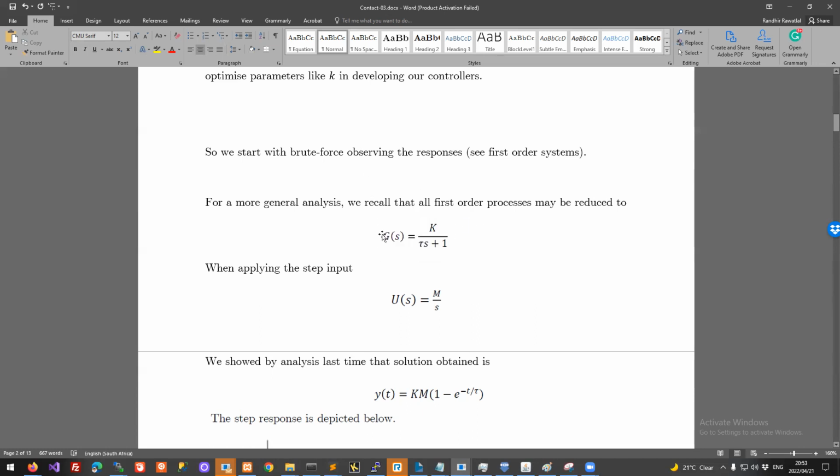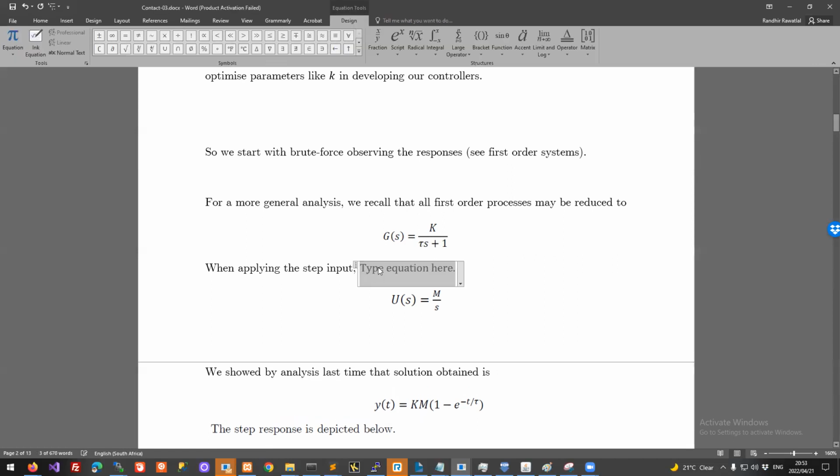So this is our first order process, and this is the transfer function. So we've divided out the influence of the manipulated variable. So there's no u showing up here on the right-hand side. It's purely a function in s and these two constants. So what this allows us to do is say, well, if we want to know what the process is actually going to do, then we can simply get that back by multiplying g by u. And so what's nice about this is we've now isolated out the type of control action we'll be taking.